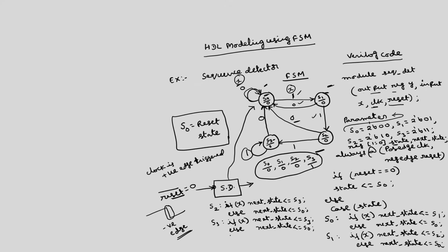So, for that you can write endcase, this case is over, assign output y, we have called the output as y, is equal to S3 equal to 1. Means whenever S3 is equal to 1, this is true, y will get 1.